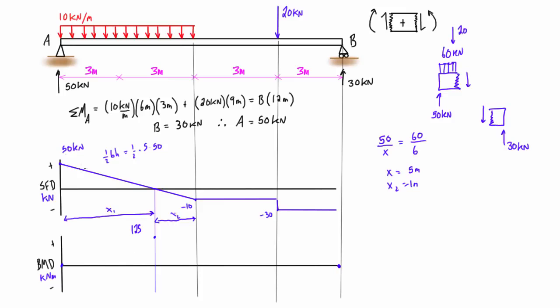So, if you remember from the Mechanics of Materials playlist that we did, where we have a shear force diagram, maybe that video actually showed up in statics, I can't remember. Anyways, in sections of the shear force diagram where the line is not horizontal, where it's sloped, we're going to get a parabolic shape in our bending moment diagram. So it's going to look something like that. And where we get this crossing 0, you're typically getting a local maximum or minimum on the bending moment diagram.